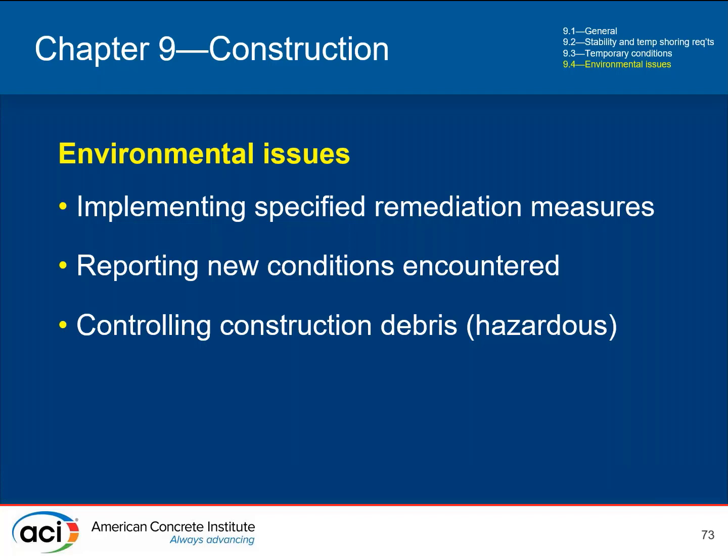Should the contractor do it? Should we get another remediation contractor? And what impact will that have? But 562 requires the licensed design professional to require the contractor to communicate to them if they encounter any new environmental conditions that need to be addressed. And then the third aspect of environmental conditions is things that are not a part of the structure, but part of the construction process and generated by the contractor. In that case, the contractor is the one controlling it, so they're the ones responsible for mitigating it.